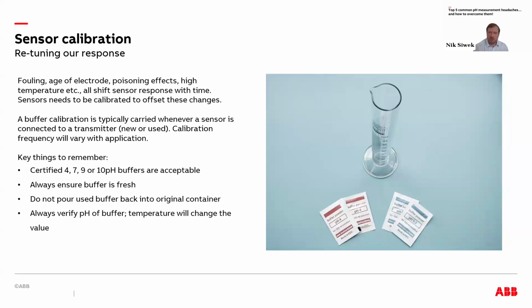Always use fresh solutions. Never contaminate them by putting used buffer solution back into the main container. Always dump it out when you're done with it, just to minimize cross-contamination. And be mindful of the fact that buffer solutions will vary with temperature, so always input the right value if you want to maintain accuracy of your readings.